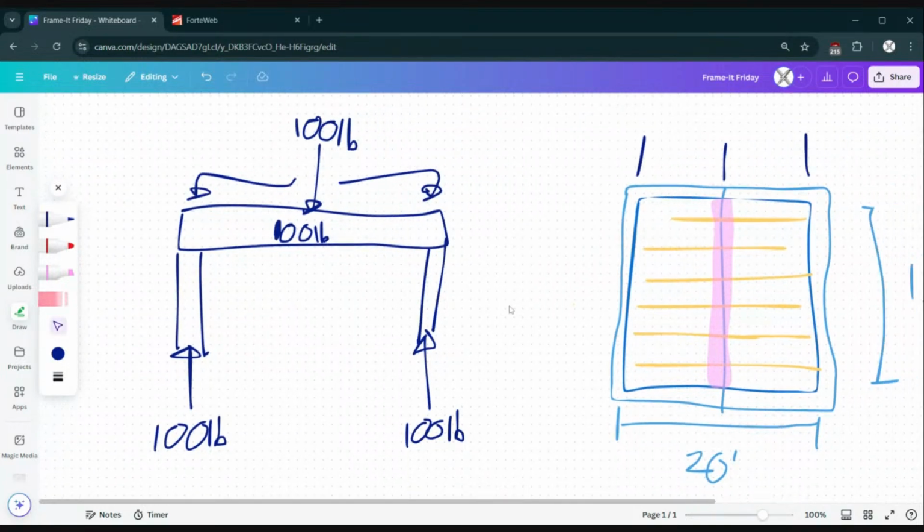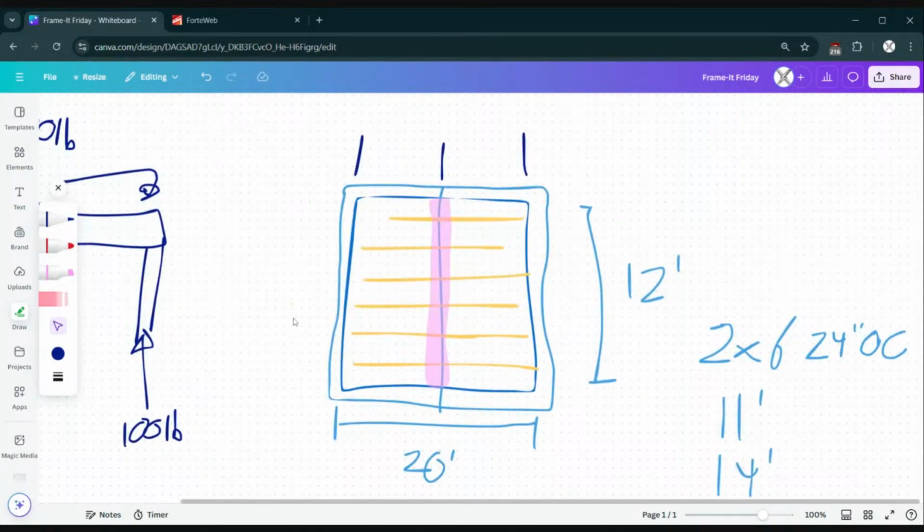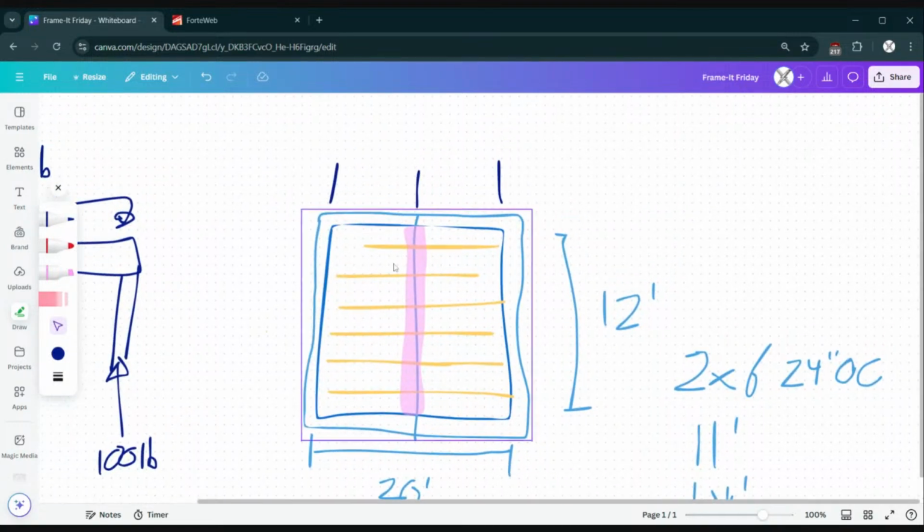And we're going to apply that over here on this building. What that looks like is basically this, top down. There's a whole bunch of weight over the beam right here. Let's think about the rafters. One rafter sits on the wall, runs up, and sits on the ridge. For one rafter, I want to know how much weight that rafter contributes to the beam. Halfway down the rafter, I would take all this weight and add it to the weight on my beam.